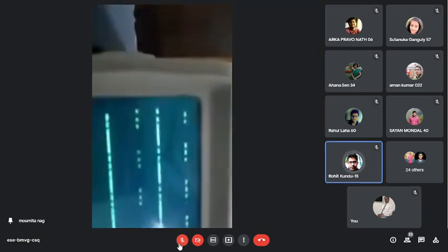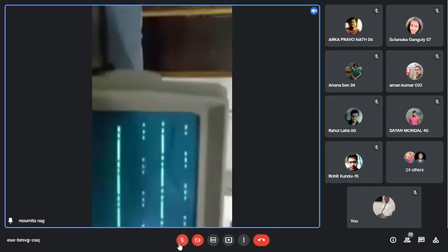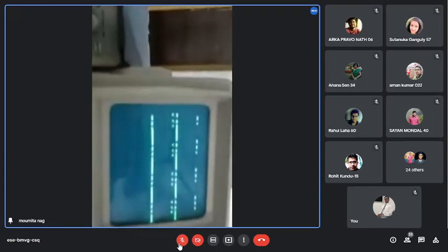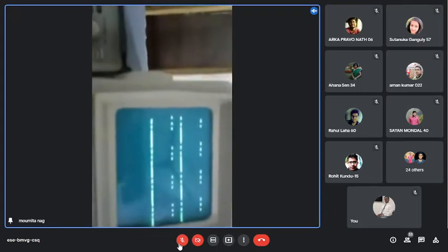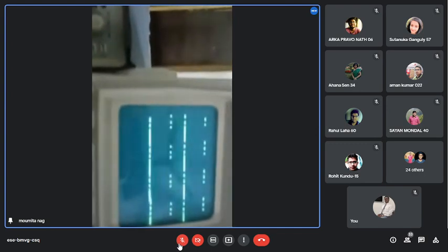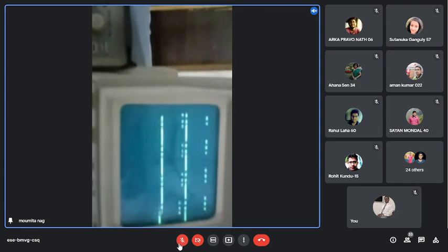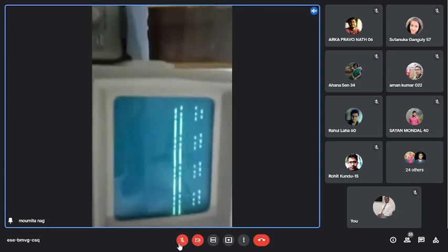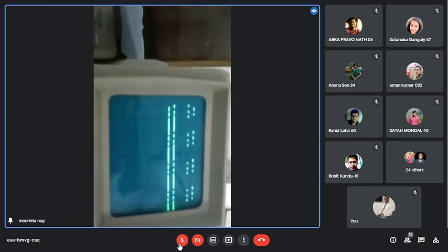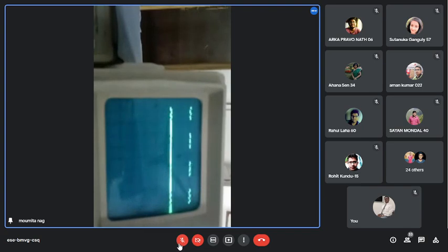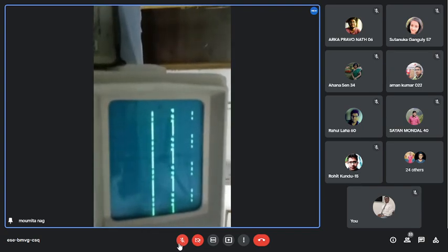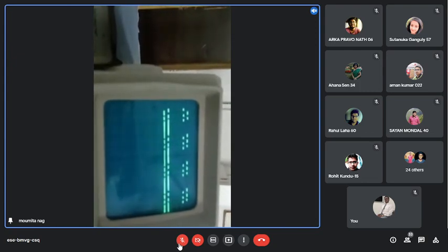Yes, ma'am. The upper one is the PWM signal, okay? See here, for the PPM signal, that is for the lower signal, when the state changes for the PWM signal, at the trailing edge of the pulse, the PPM signal occurs. See here. The lower one is the PPM signal. See, at the trailing edge of the pulse, the PPM occurs.